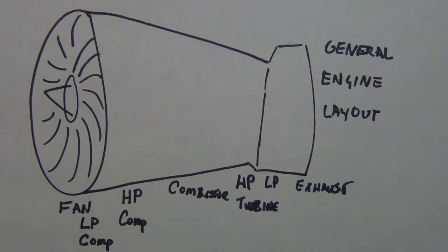You don't have to memorize this, but just letting you know that there's a different number of stages for each of those, the dash 5B and the dash 5A. On your 5B, it's a 4-stage. Your 5A has a 3-stage axial booster. Okay. Your spinner front cone.